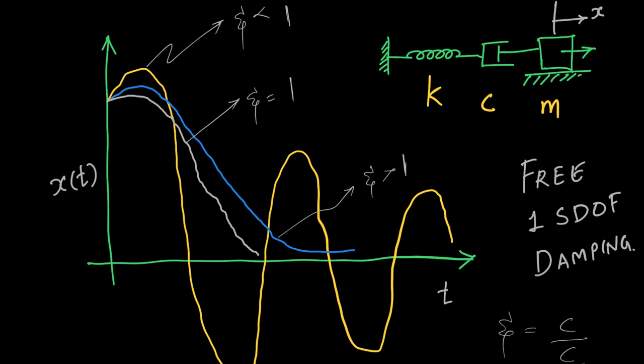Now from this figure you can see, when I'm increasing the amount of damping present in the system, or in other words, when I'm increasing the zeta value, when zeta is less than 1, motion is harmonic. It is decaying, but it is harmonic. I say it is decaying because, as you can see here, the amplitude of the waveform is decaying. To be more precise, it is decaying logarithmically. So when you increase the amount of damping, the motion changes from periodic to aperiodic.